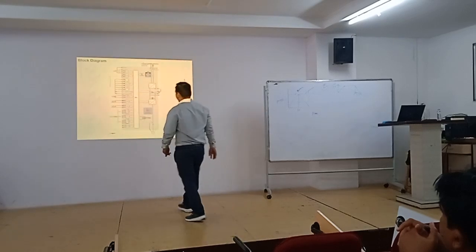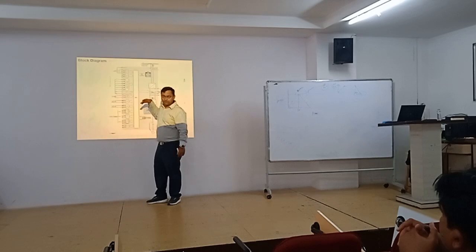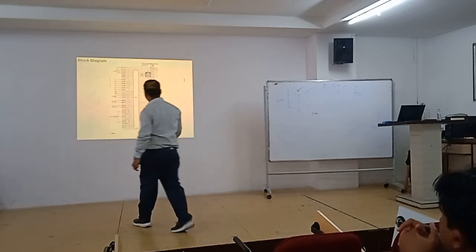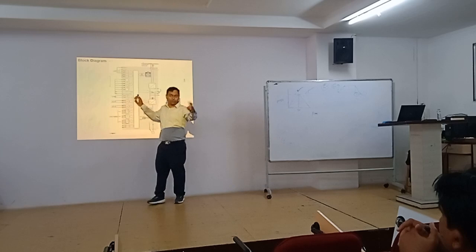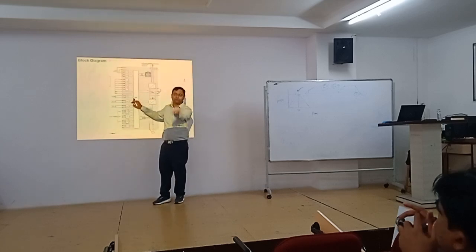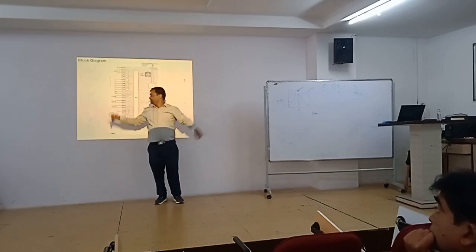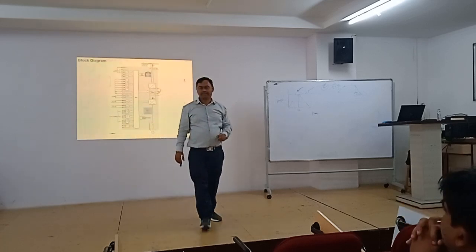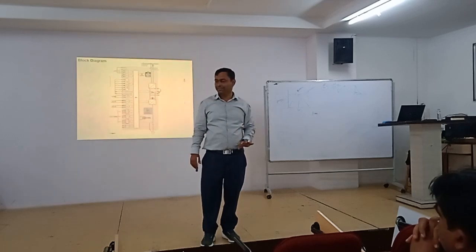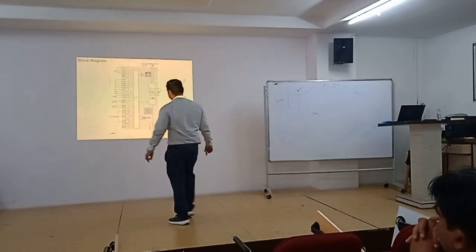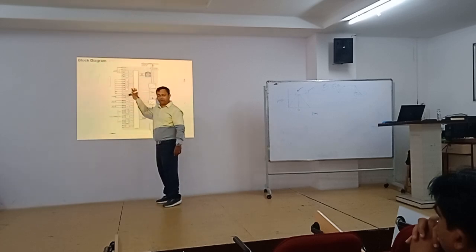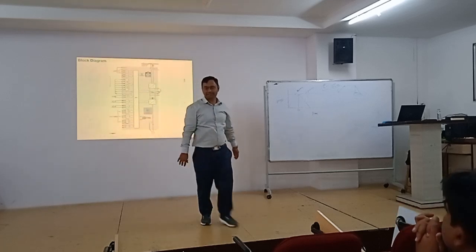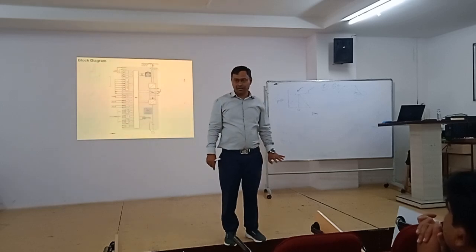Sometimes we also have the digital output and the analog output of the VFD. Using the digital output of the VFD, you can start other motors. Suppose you want to operate two or three motors in synchronism. When this motor reaches 25 hertz, you start the second motor. Based on this, you will command the third motor to start. So a lot of things you can do very easily. This will be there more or less in all VFDs. And the main thing is this one, control: how you are controlling it.